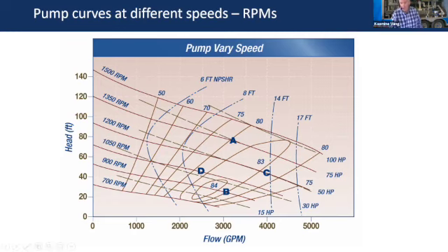Hopefully that answers your question, Charlie, because you're absolutely right. There is a limitation, at least that's on there. But the old standby was no slower than half speed. Now the new ones, a lot of times, can go slower than that. So if you have the right equipment, just make sure you do. If you have one of the older VFDs, they may not want to. I think that would be, especially if you run it over an extended period of time with no load on it, that's when it comes into play on that electric motor mostly. It won't hurt anything on the pump, the bowls and impellers or anything, I don't think so.